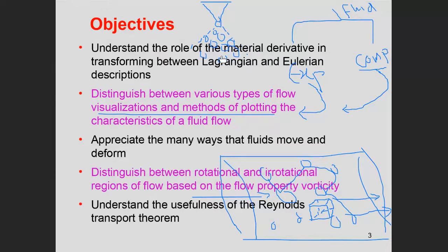Lagrangian approach is better because you can say, okay, 1 million particles is enough to model the spray combustion, right? But if you have a domain like this, a pipeline, it is difficult to use Lagrangian, and therefore Eulerian is important. So gentlemen, this is briefly fluid mechanics.